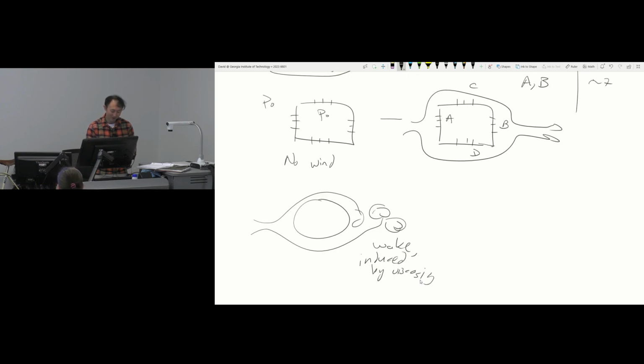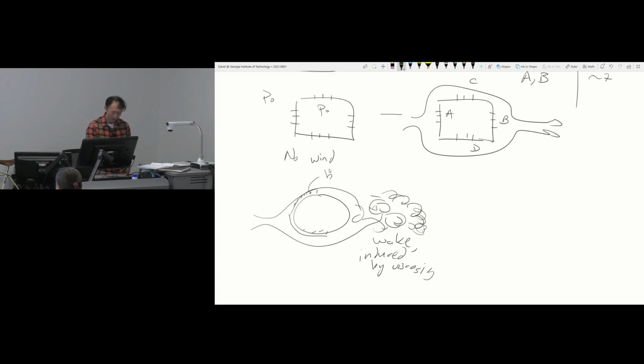Specifically, there's this really thin boundary layer where you have vorticity. That's called the rotational region, and that vorticity is shed and goes downstream. I know you calculated vorticity for some previous homework, but it's almost like density. It's something that the fluid has, and it carries it with it. So once you have vorticity, it's shed as this stuff is going away. And there's the boundary layer, and this is a sports ball.